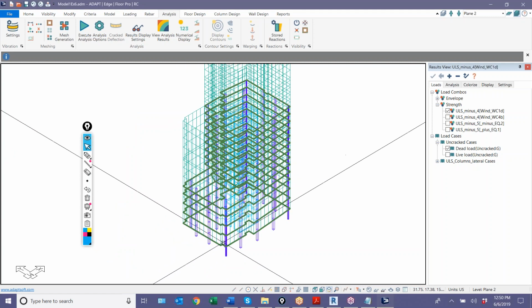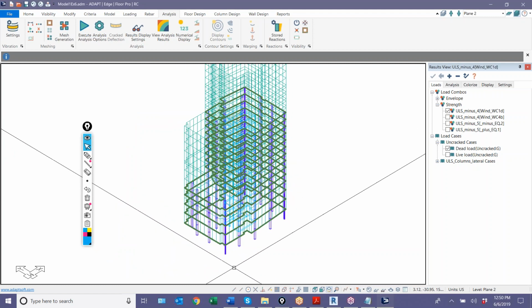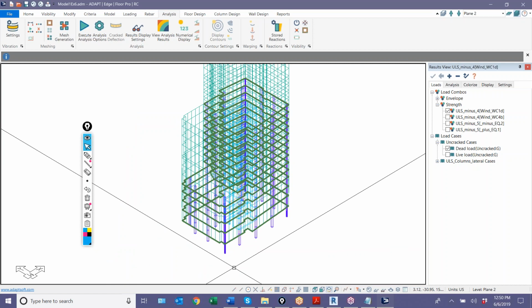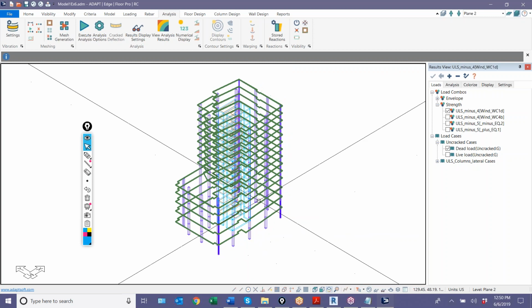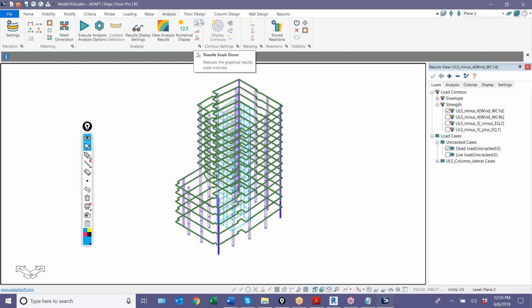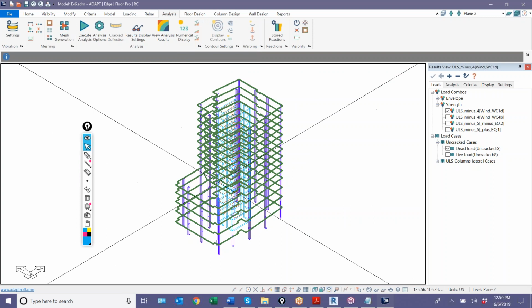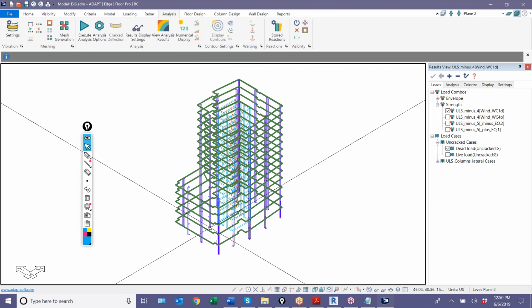Okay, now what we're going to do is process the tributary loads. It doesn't have to be in this sequence. I could do tributary loads first. I could do FEM first. I have to run FEM because I have lateral load cases as building load cases. Let me go back to my default display. So now I'm actually going to run the tributary solution. So I have the possibility of enveloping the vertical reactions in the columns or walls, let's say the axial load, between the FEM solution and the tributary.